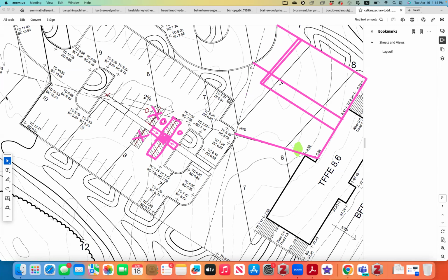Let's not do that. Let's separate the trench drain from the ramp, because a trench drain has a vertical volume. It goes down, right? So you wouldn't want a trench drain to overlap with a ramp. If we put the ramp over here, you could put the trench drain there, but I would say this is a better spot for that ramp going up.